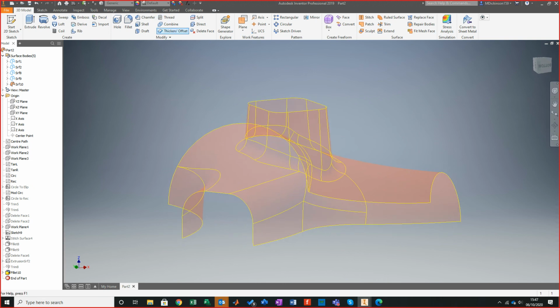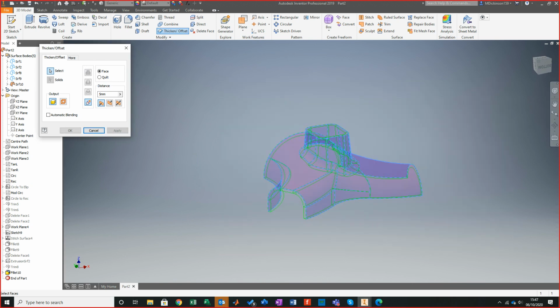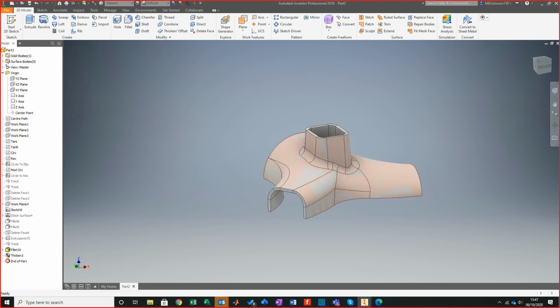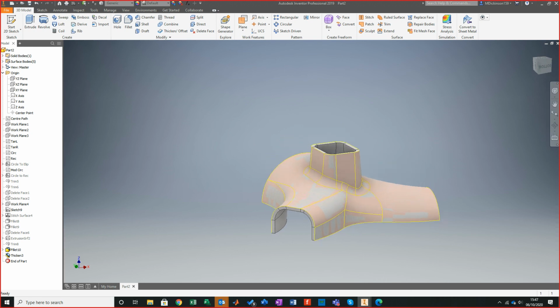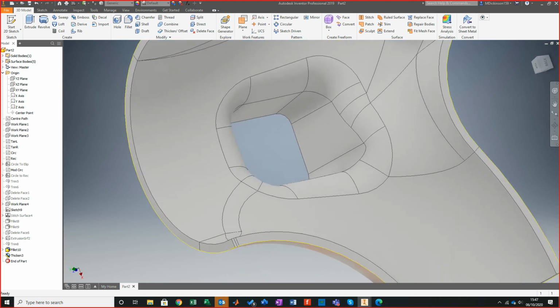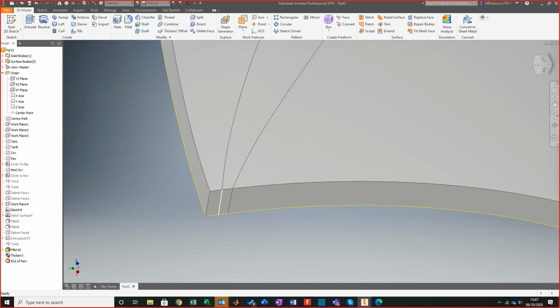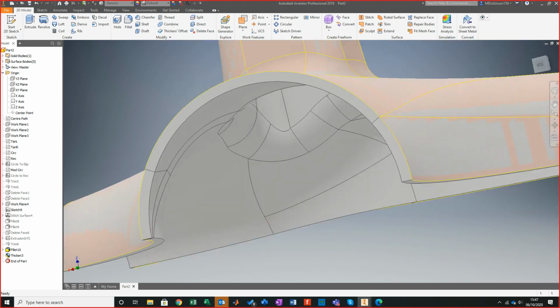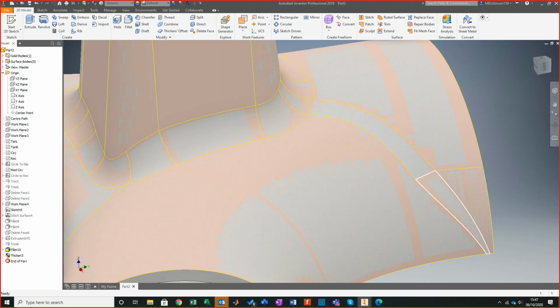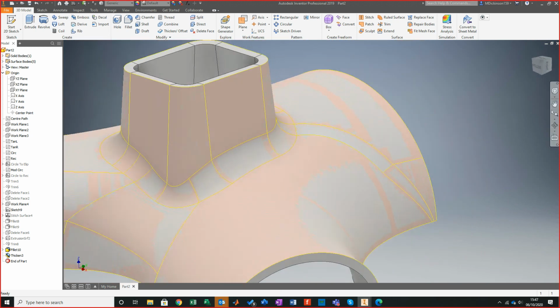So what I'll do now is bring that thickening in, and I'm going to highlight the whole thing. I almost need a drum roll. And click OK. You almost want to get up and cheer. So there we go. We got that thickened part, and just to recap, it was coming from a small needle surface stuck at the edge of here, and it was coming from the fillet that passed across to here. When it hit here, it created a knot.